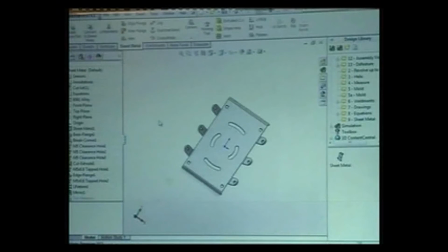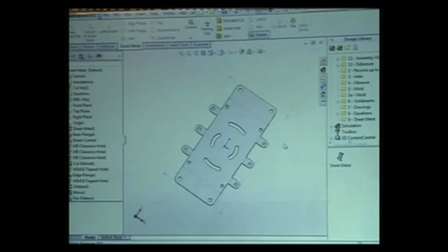Say I want to have a bend calculation table done here. I'll just click OK for this. So automatically this bend calculation type of deducing the bend allowance is incorporated inside sheet metal now. Let's look at the flattened piece. If I want to check this blank sketch, you can see that it has been reduced. Its length is now 189 millimeter.